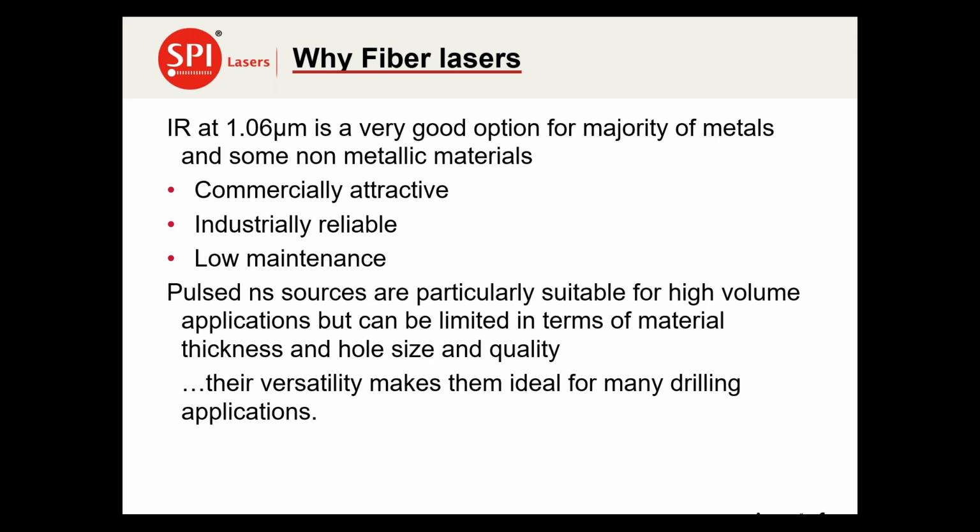Pulsed nanosecond laser sources are a subset of fiber lasers, and these are particularly suitable for high volume applications, but can be limited in terms of the material thickness and the hole sizes, and in some cases the hole quality that can be achieved. But their versatility makes them ideal for many drilling applications.